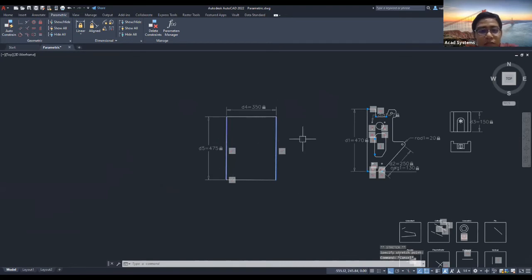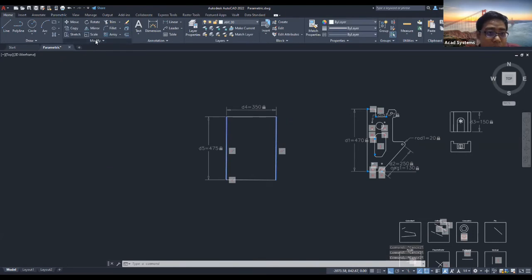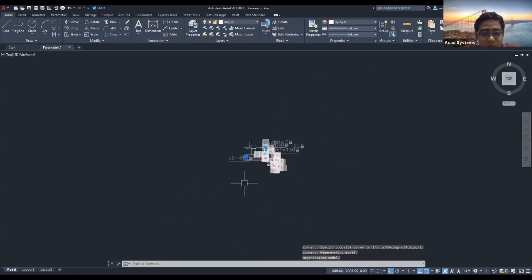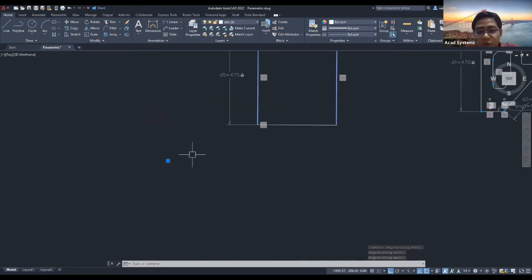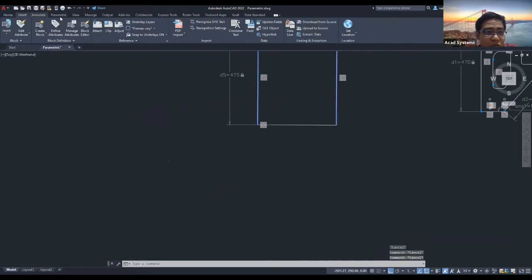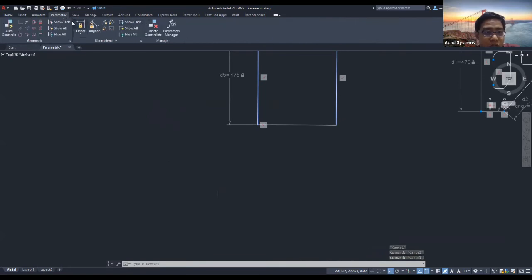So I can also lock this one into some point. For example, I have some points from here. Right, so inside of Inventor, usually we have the origin point be this, so this XY axis, the UCS. However, the UCS in AutoCAD does not lock, but I can still use my point over here by using the draw, and I can use my parametrics to lock using these fixed constraints. So I lock this point. This point does not move anywhere. I cannot move it.